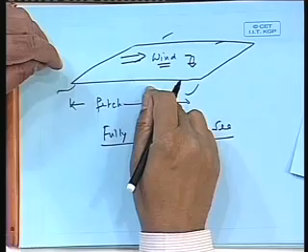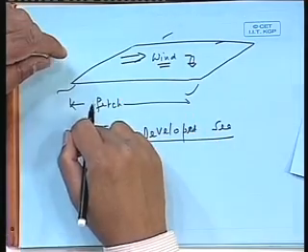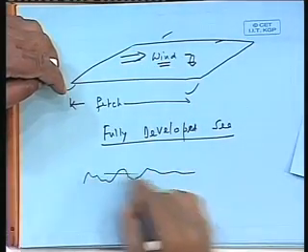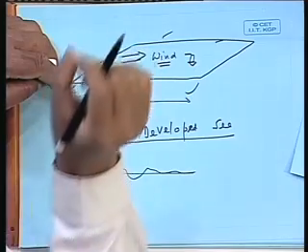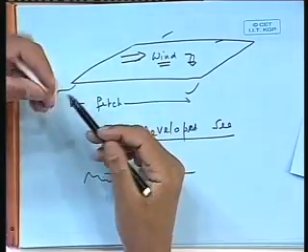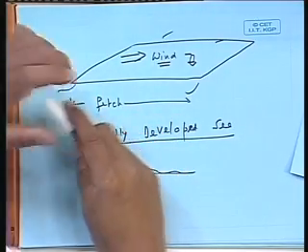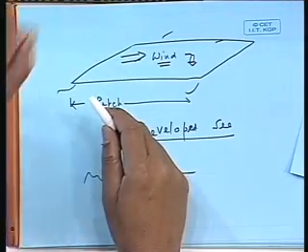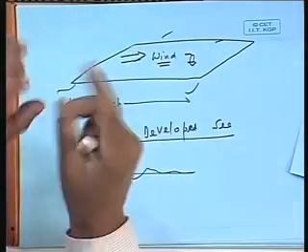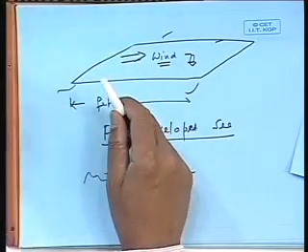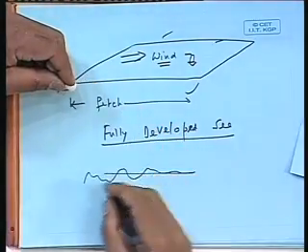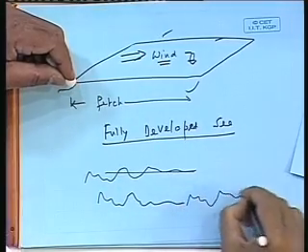The main point is that if I take this random signal and break it down into components, the energy per unit area of that surface remains constant, because energy is a conservative principle. If wind was blowing at, say, 20 knots for a long time, then the wave that has been created would be of such a nature that the total energy over a unit surface area remains constant. It may look different, it may have a different kind of distribution. Today it may look something like that, then it may look random.